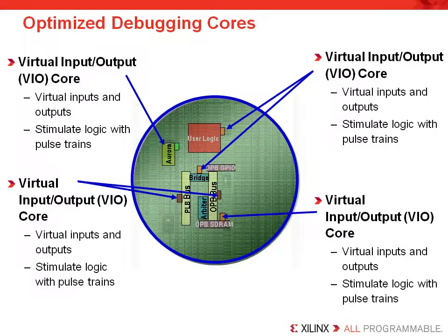The ILA core, or Integrated Logic Analyzer core, is a capture core. It can be used to create custom triggers that, when activated, cause the storing of data during circuit operation. These conditions are placed by you to control when your system signals will be stored. Your sample signals are then encoded in your FPGA's block RAM for later retrieval via JTAG. The ILA core allows the user to customize the width and trigger ports so that different sizes of data can be retrieved. The ILA core is a basic core used in most HDL designs.